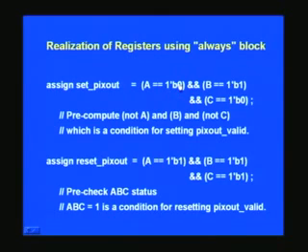Suppose you want to have it in decimal, what you need to do is just replace this by D. Suppose you have some 8 bits in a particular case, you don't have to write 8 zeros, just 1 0 is enough, it will take care. Suppose you want an octal representation, replace B by O, and for hexadecimal, replace it by H, and so on. Any bit precision you can use the same thing. And note that 2 equals signs are there, that means logic. You could have straight away put A and B and C also, that would also serve the purpose here. This is again put deliberately in order to explain the alternate way.